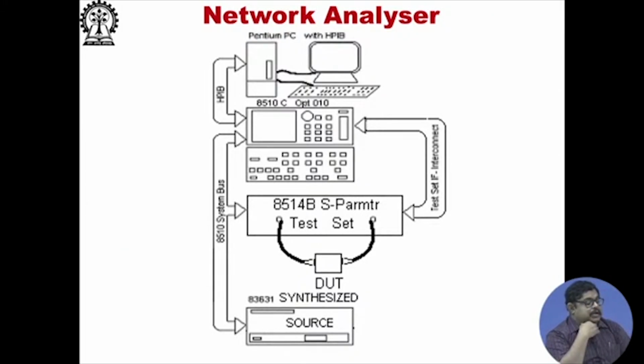This is the architecture of the 8510 network analyzer, a very popular network analyzer invented by Hewlett Packard company in the early 80s, a very successful network analyzer. The 8510C had this box, this controller, and this S parameter test set. It has a source, and there were Pentium PCs with HPIB buses.